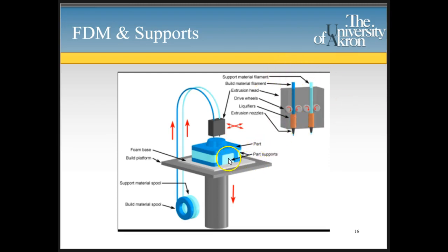And then there are various methods of getting rid of this. Years ago, I had an industrial 3D printer, and the support material was water soluble, so it would dissolve away. So you would take the finished part and place it in an ultrasonic tank with a fluid in it that would help to dissolve the supports, and the ultrasonic would help get rid of it as well. So you basically put the whole part with supports into the tank and run the ultrasonic overnight, and when you came back, all the support material was dissolved. So that's also another popular methodology.